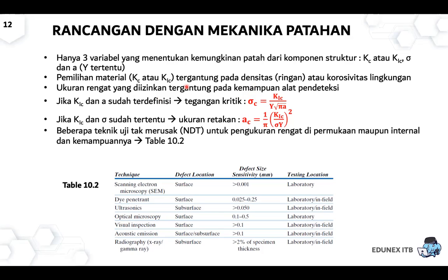Okay, the second one, if you have the K1C, and you also know the applied stress, then you have to check what is the maximum crack that you're allowed before it makes a fracture. So this one here, that would be to check. So the equipment will be safe as long as it has a crack, but the crack doesn't exceed these millimeters.